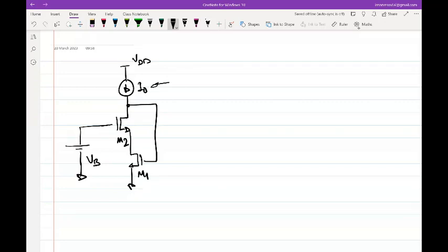The question essentially what I am trying to ask is, given that there is a constant current source, which transistor in this stack is responsible for absorbing a change in current? For example, if I0 for some reason changes to I0 plus delta I, which transistor will be responsible to ensure that this current gets absorbed while ensuring M2 and M1 are in saturation?